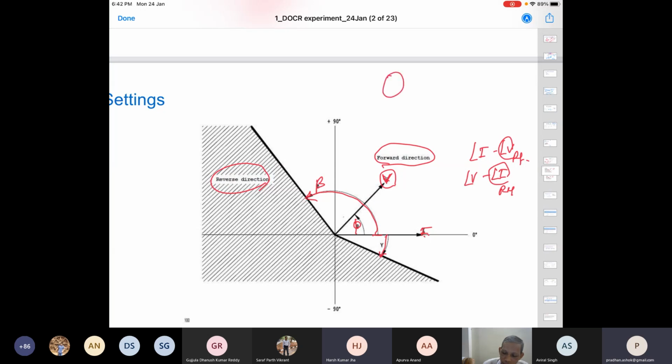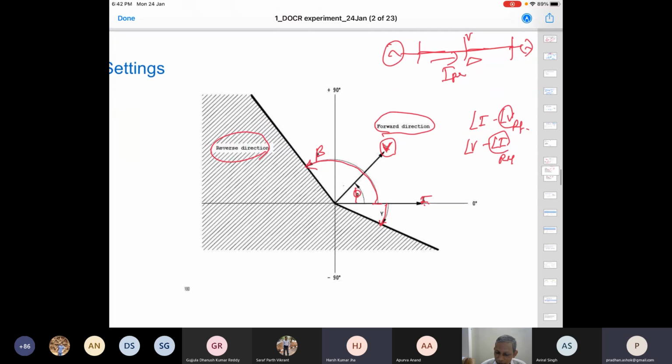What we would like to see here is, when you are looking in the forward direction, the relay happens to be there, and the corresponding voltage and current are like this. There are so many modulating factors. That's why I don't talk about something like 0 to 90 degrees. The pre-fault current I pre, the corresponding fault path impedance, and the arcing resistance are all there.